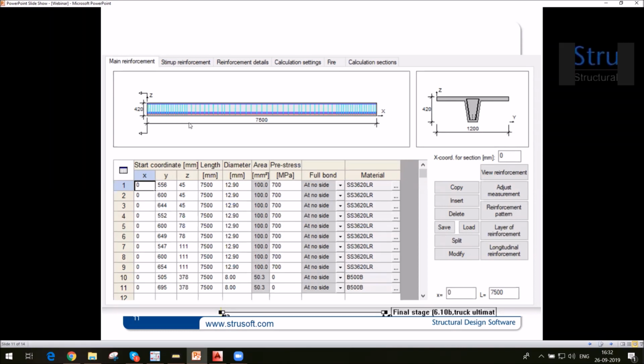This is what I wanted to show you is stirrups reinforcement. We can customize the stirrups as per our requirement. Like I'm reducing the spacing in the initial stage and then I'm optimizing it further. So that's possible with the software. I'm designing a T-beam over here.